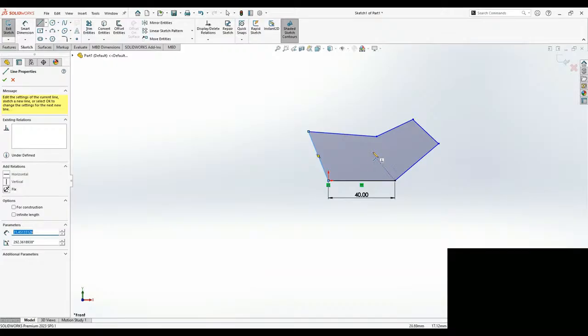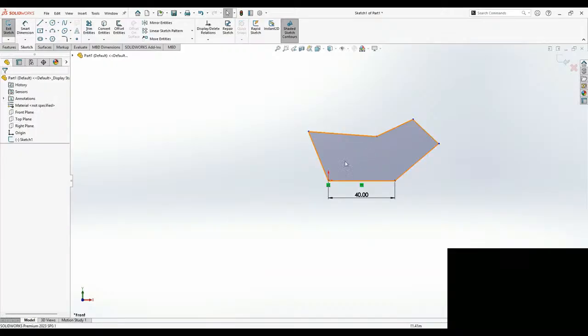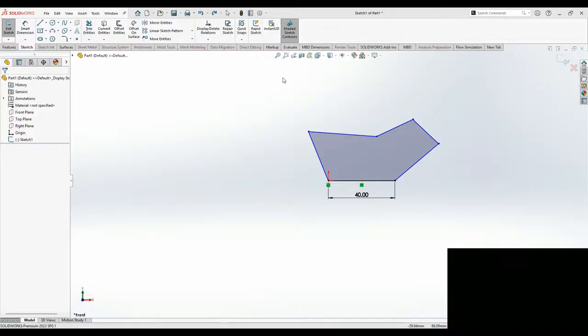I would like to have one more circle here. So my shortcut is C for circle. I already set it. If I directly press C now, the C for circle command will be activated. Right now I don't see that. So what you can do is I'll directly show you live how you can customize. Go here, customize, click on it, go to keyboard shortcuts, search here for circle. So there is no command for that.